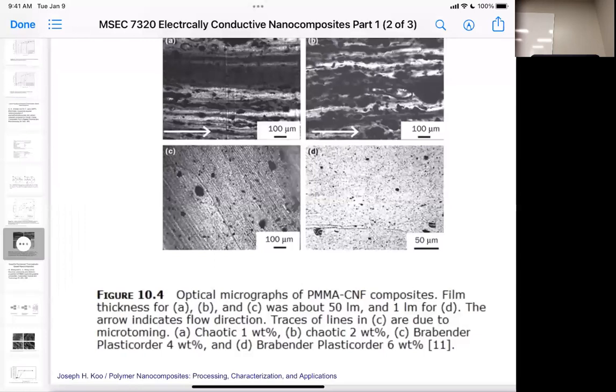So is it important that they should be dispersed and should be in the line of the current or something? Yeah. For conductivity, you want the lowest resistance between, okay, think of the percolation threshold as your serial resistance, okay? So the resistance to go from here to here, right? So you have your nanoparticle, you have a resistance between the two nanoparticles. What you want is the lowest serial resistance for that system. So you can have well-dispersed particles that are correctly spaced, so the hopping distance lowers your series resistance, or you can have almost like wires or sheets of conductive material. Even though they're not well dispersed, they'll still be able to conduct. So you can have it either way.